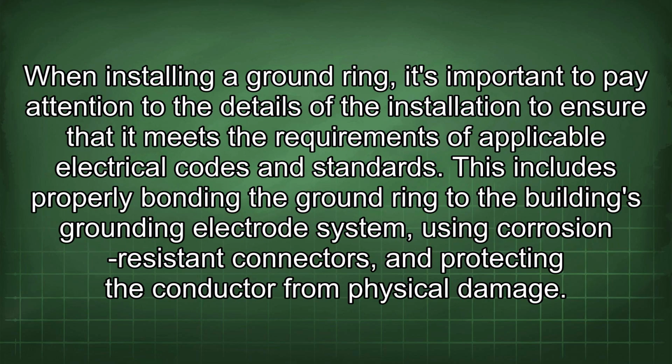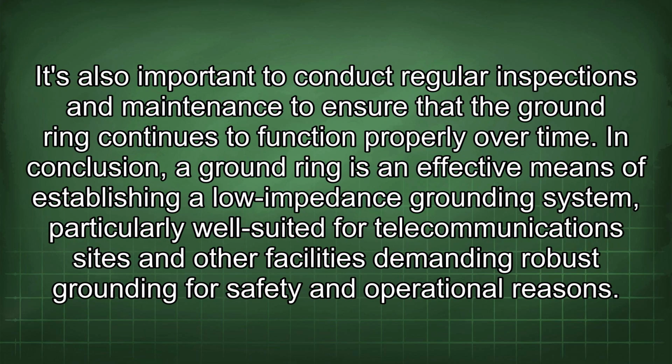When installing a ground ring, it's important to pay attention to the details of the installation to ensure that it meets the requirements of applicable electrical codes and standards. This includes properly bonding the ground ring to the building's grounding electrode system, using corrosion-resistant connectors, and protecting the conductor from physical damage. It's also important to conduct regular inspections and maintenance to ensure that the ground ring continues to